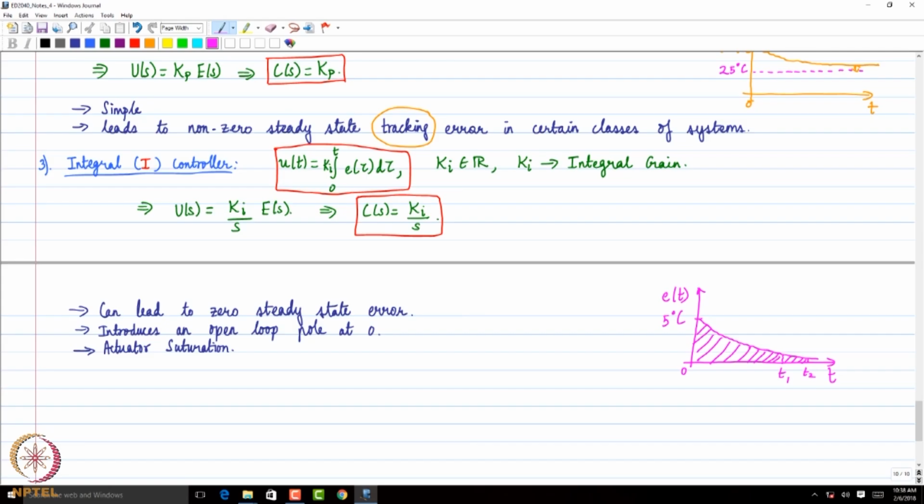I reach actuator saturation. With such a controller, although in theory I might be satisfying some performance requirements, in practice I would not be able to reproduce those performance requirements. Because I may say, settling time would be so much with 1000 newtons, peak overshoot would be lower than, let's say, 5% if you give 1000 newtons. But my capacity of the actuator is only 100.